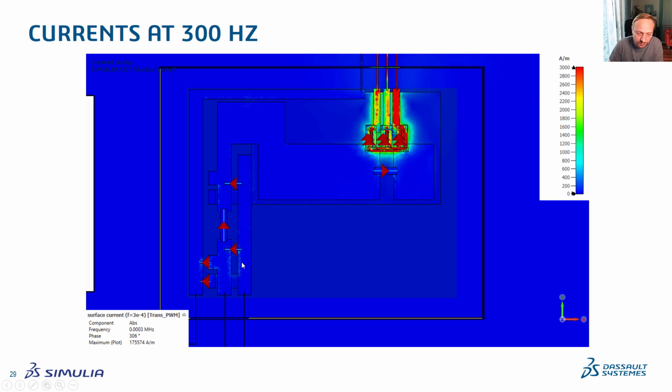I mean, there are some small values here, but in this arm, the 300 Hertz signal does not flow. It flows to the motor, and that's exactly what you see here. It's the three-phase 300 Hertz with a 120 degree phase shift, as you would expect. That's exactly what you have designed the inverter for, together with the PWM. So this is just a cross check.